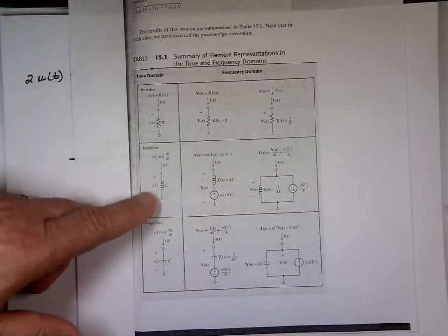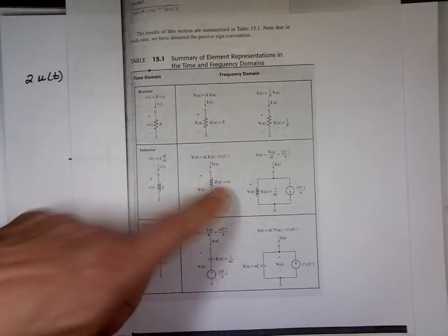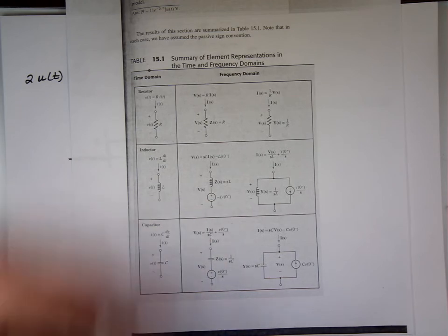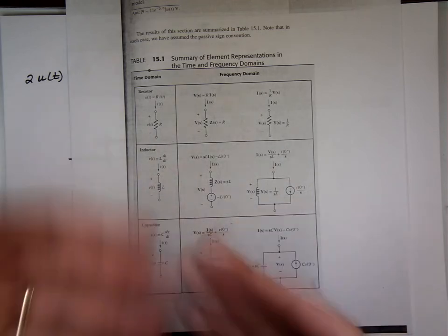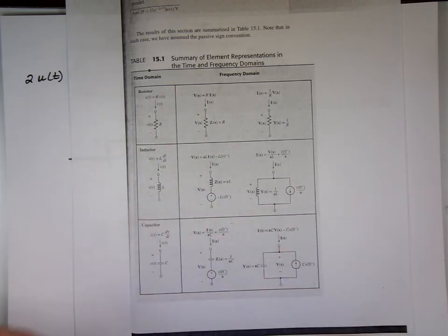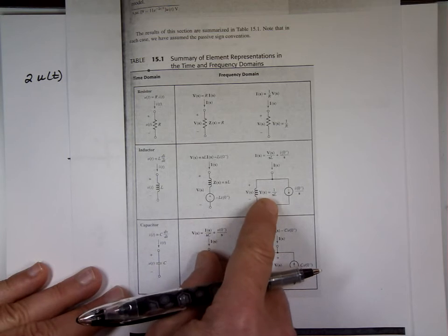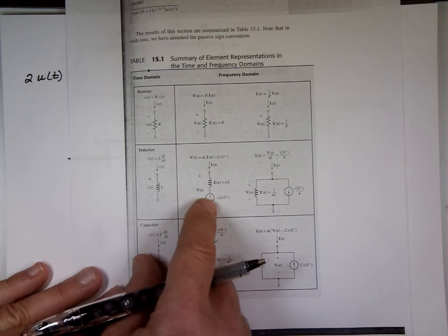If you have an inductor L and you want to find the voltage there, we make that inductor sL with the voltage source. But if you try to find the current through that, because that's the integral, and the Laplace of the integral is 1 over s. So that's why you have 1 over sL plus I sub 0. Notice the direction of the voltage here.